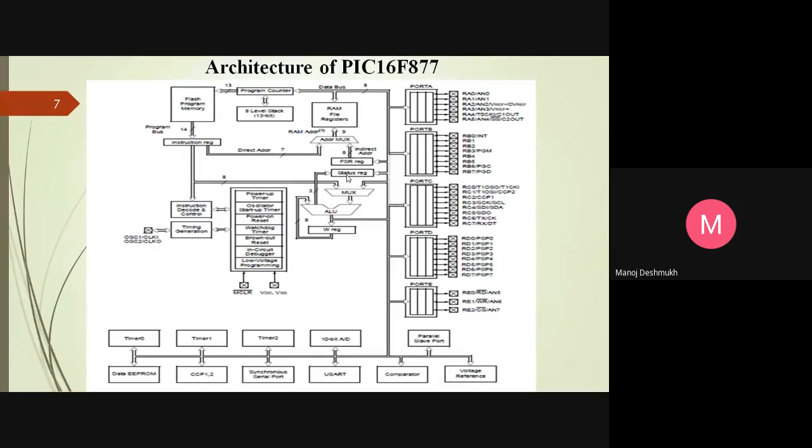Okay, timer interrupts are there, external interrupts are there, ADC is also considered an interrupt. Here the status register is a separate 8-bit register, we will see afterwards. The file register does not include any specific bits or bit allocations. It is only a blank register, like the SBUF register, if you remember SBUF. It will directly access the content.